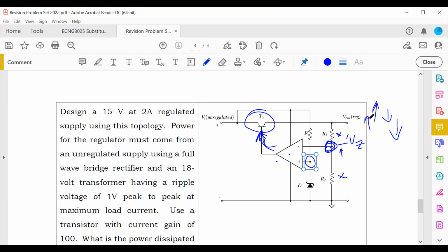Right? The previous circuit had the little transistor here. So what had happened is that you clamp here by the Zener voltage, and here would fluctuate up and down depending on what the power supply was doing. And if it went up, then remember this has to maintain 0.7 volts to keep the transistor on. If it turns on higher, you're trying to increase the voltage here, it is going to pull more current through the transistor to try to bring it back down again and get that back down to 0.7 volts. So it's the same sort of principle. But all the op-amp is doing is trying to maintain the voltage at these two input terminals to be the Zener diode voltage.